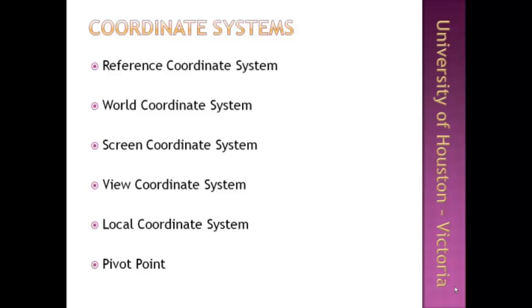Your coordinate system is basically the tripod at the lower left of each viewport, and this tripod's axes are locked to the world coordinate system, in which the xy plane is always the ground and the z axis always points up. This is made so that you can orient yourself no matter where your objects are located, how they are rotated, and the size of the objects.